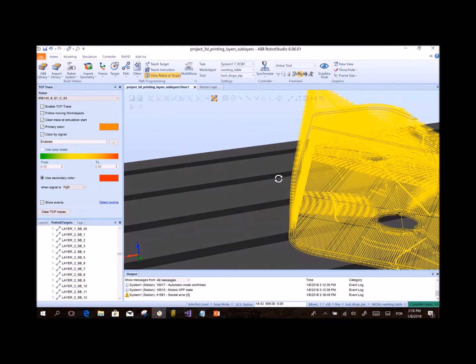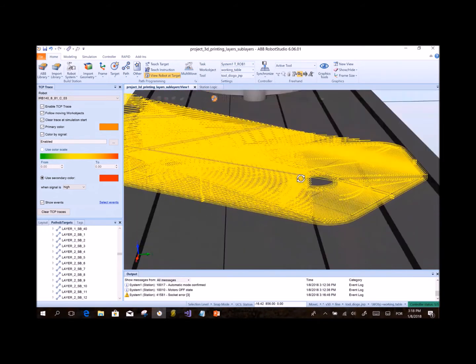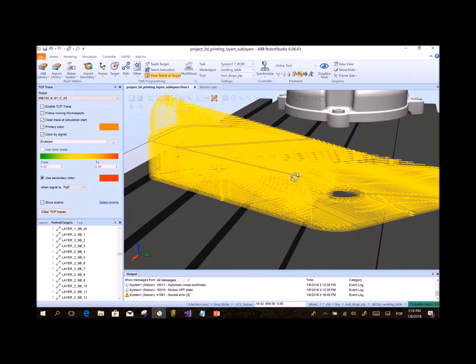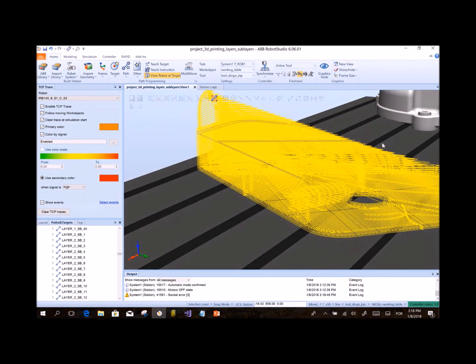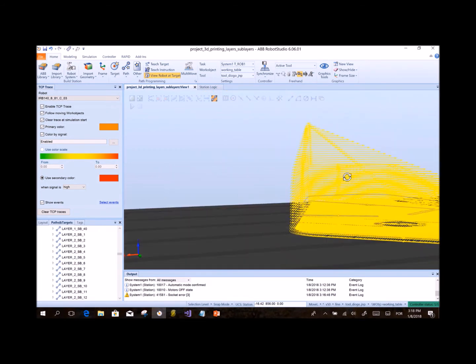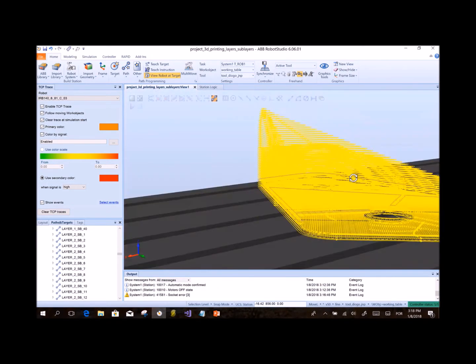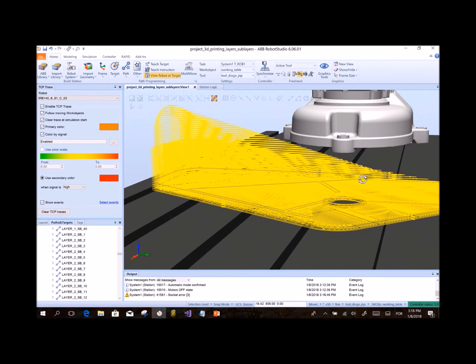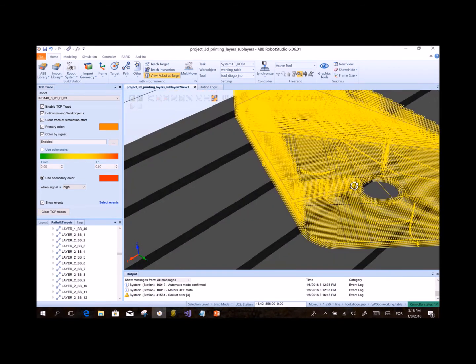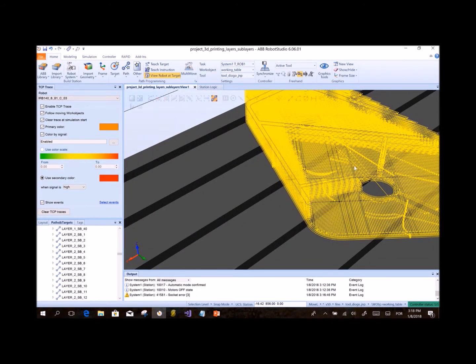With the program we have done, I extracted the XYZ positions and generated orientations for this robot, an ABB IRB 140, and also automatically generated the RAPID code to execute these paths, and the result is these represented paths. But as you see, this is a little bit complex to see, so we will hide this